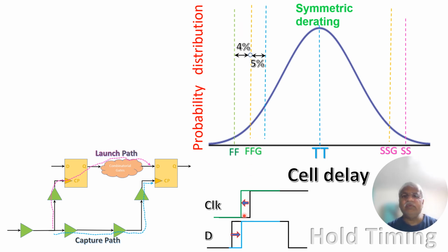So now we will apply that in the early paths to the clock. So the data clock is coming slightly earlier, and we will see here we are applying the late derate. These are the late derates. These late derates are applied to the launch path. Hence, data is coming slightly late. So because of this, now we are mimicking a hold scenario, a pessimistic scenario.